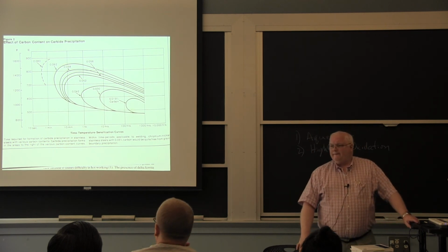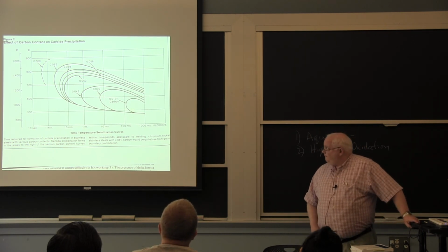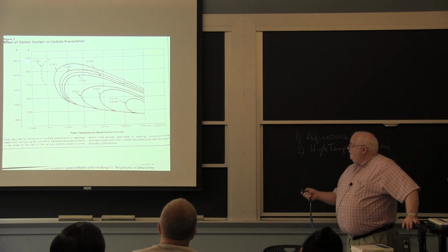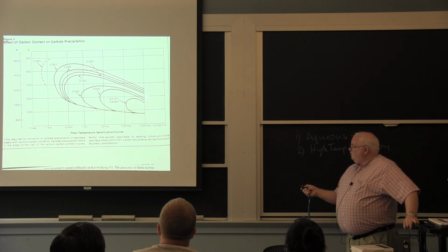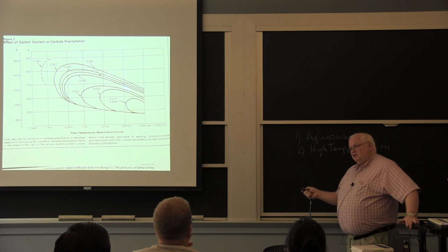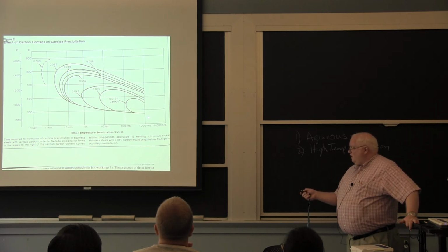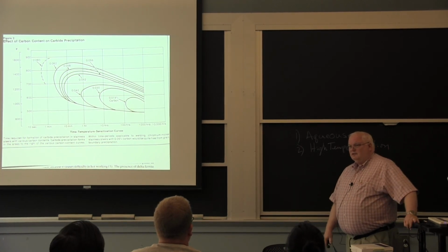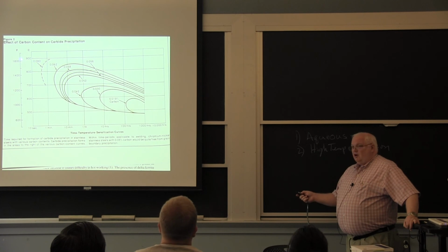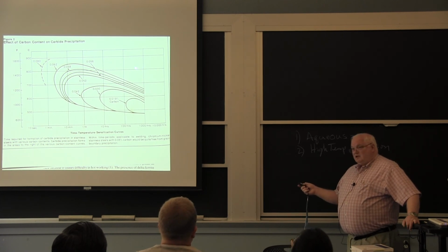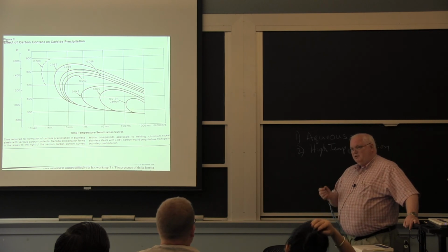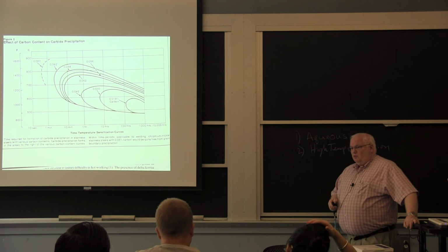So you're at like 800, you have 0.08. Yep. You go to like 1,000 hours, the precipitates dissolve. No. This is just to start the reaction. I've seen these plots where they show you the finishing, but this one they're trying to show you the carbon content. If you put the finishing reaction on top of this, everything would just look like a mess. Okay, so this is the reaction starting. If you go to 1,000 hours at that temperature, it's going to be down around 6% chromium in that region. Okay, and so it'll just be even worse.